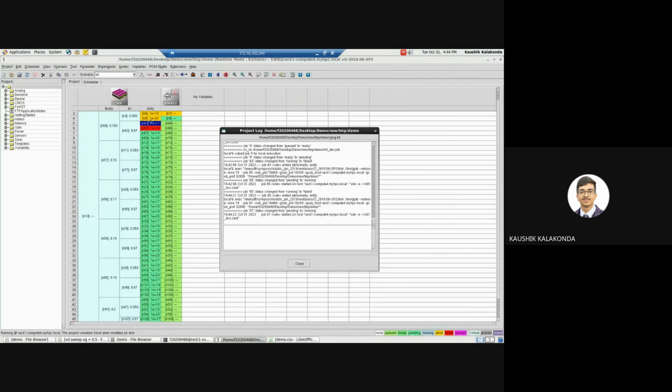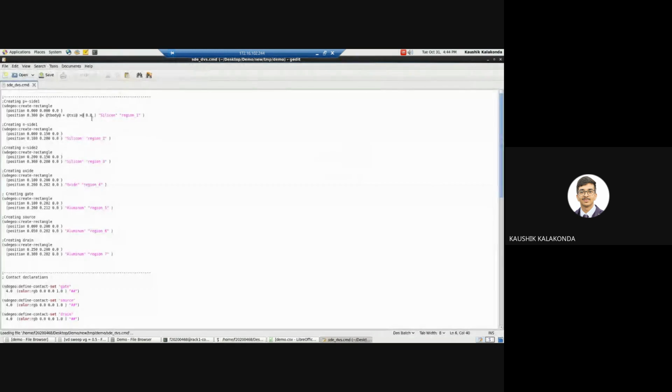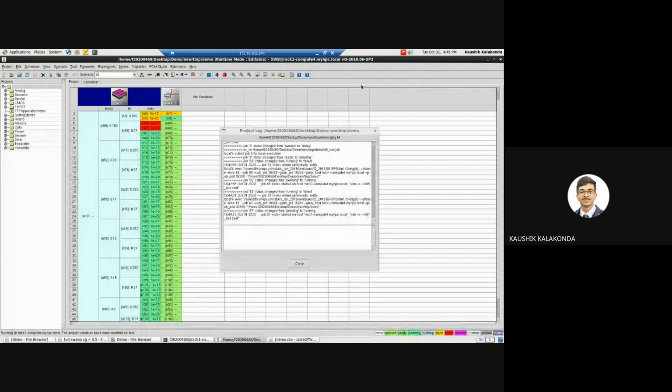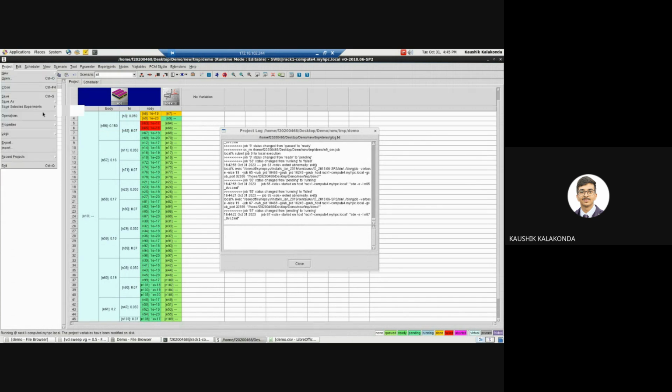The reason we got this is that we didn't change all the nodes. If we go here, I've changed only the first line. The remaining lines also should be changed. Since they're not changed, one material is overlapping the other, and we are getting the wrong result. So I got to know that I need to change all the nodes.